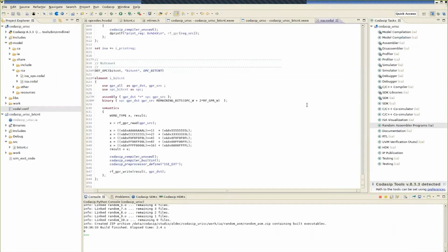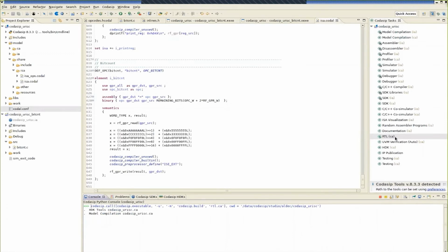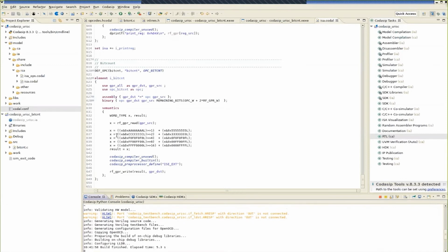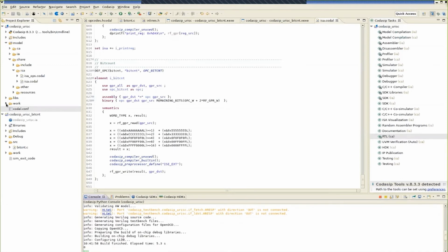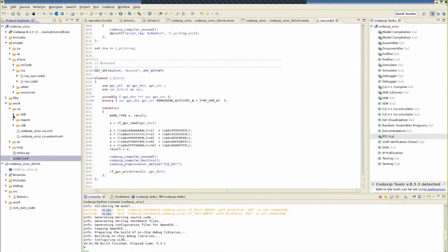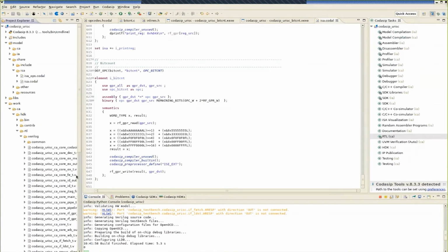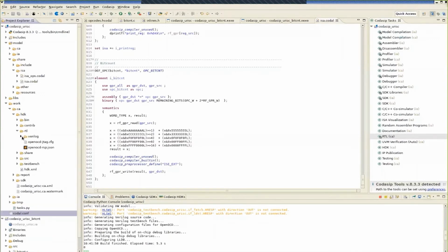The next thing we can look at is RTL. RTL is important because we want a synthesizable version of the extended core. So let's generate the RTL. We also want to have test benches. So that's now built. So if we go into the cycle accurate area of Studio, here we see a bunch of RTL programs which describe the URISC core.